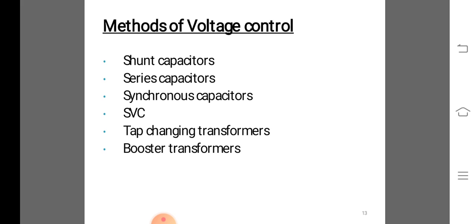If the total line reactance is high, series capacitors are very effective and stability is improved. With series capacitors, the reduction in line current is small. Hence, if thermal consideration limits the current, there is little advantage from this. So, shunt compensation is to be used.